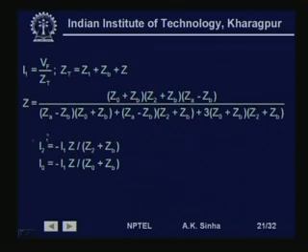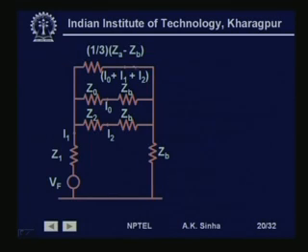So, if we do that, then we have this I1 computed like this. I2 is a part of the current which is flowing in that. So, this can be written as minus I1 Z divided by Z2 plus ZB, and I0 will be minus I1 Z divided by Z0 plus ZB. So, since I1 is flowing and the total impedance, as we had seen, is this impedance Z, a part of this goes through this and the rest will go through this.